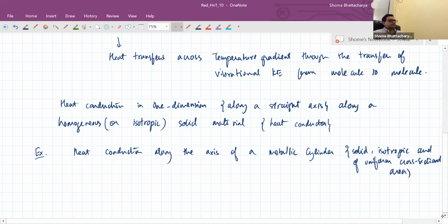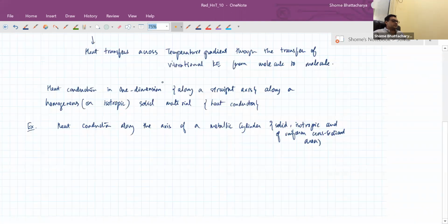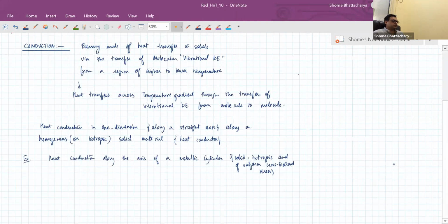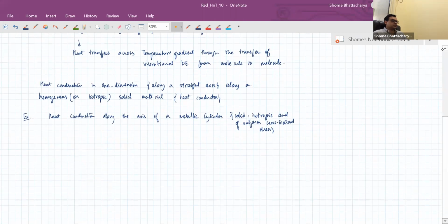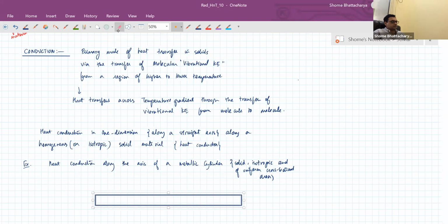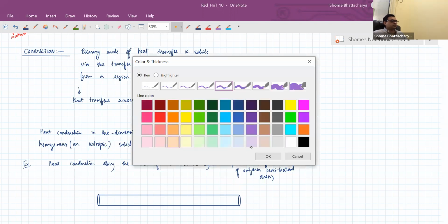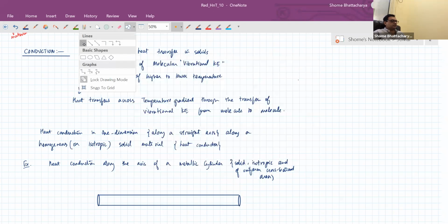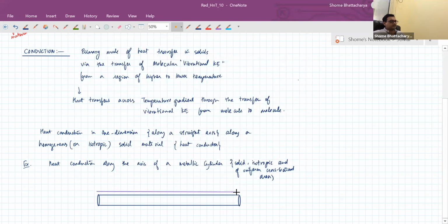Okay. So just imagine you have a solid metallic cylinder and we are studying its properties with relation to heat conducting across its own axis or across its symmetry axis, you can say. So to set up an experiment like this, what we will have to do is first of all, we will have to insulate the solid cylinder on its curved surface so that heat cannot escape along the curved surface, and heat only transfers or conducts along its length.